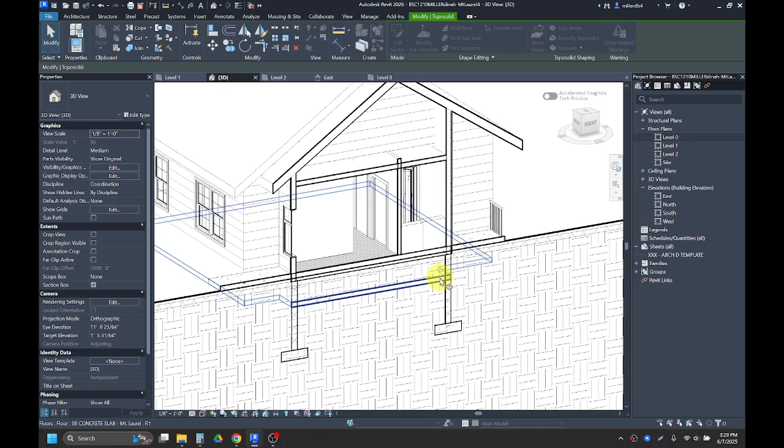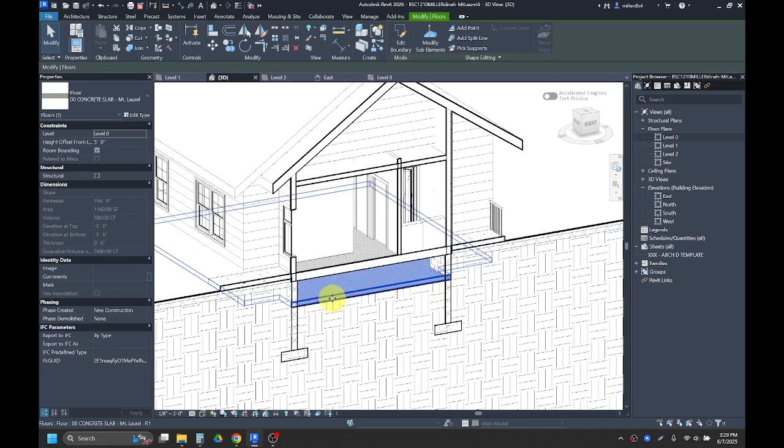And then you're going to click on that floor that you just made. And essentially it's going to just dig out all of the dirt from inside of our building. If we decided to move this floor, so if I decided to put this floor at, say, negative, or not negative, but rather 3 feet instead of 5 feet, it will still just move where that gets excavated for it.